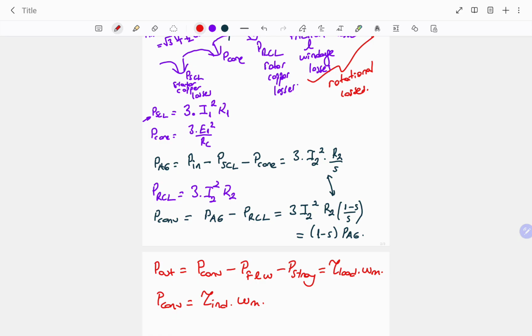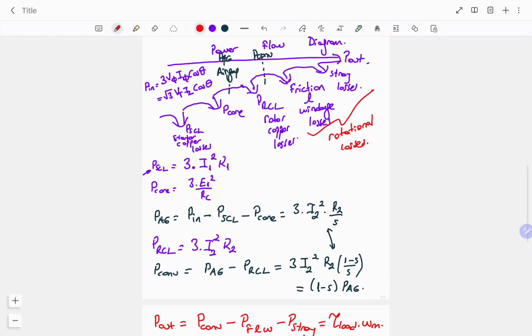Related to rotational speed, we can say the air gap left side has Ws. If we want to calculate any parameters related to speed, we should use Ws, but after the air gap, our speed for each calculation must be Wm.